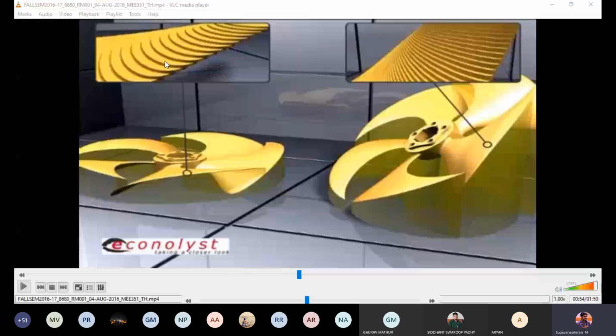But if the slope angle is within 20 to 80, just a range I am giving, but it varies from machine to machine, that will produce a very high staircase. So the first region is giving a high staircase. Because of that, you will be getting very high roughness on the printed part. Whereas in the second case, you won't get that roughness. Still, the second part also has a staircase effect, but the roughness value will be less compared to the first case. So that is the difference in terms of what kind of roughness you require.